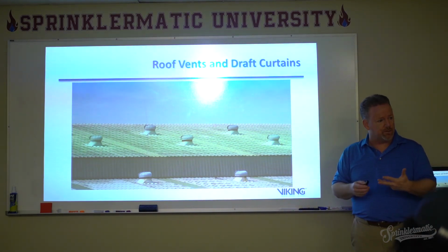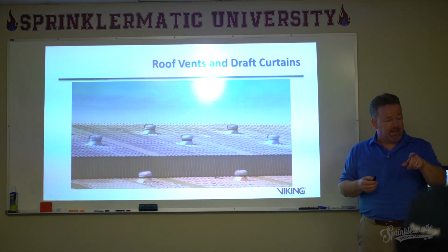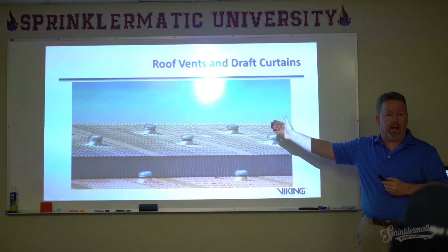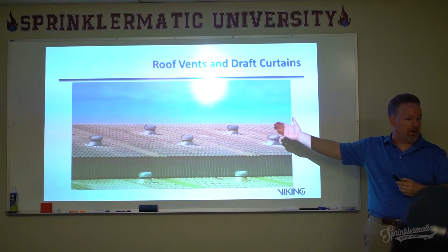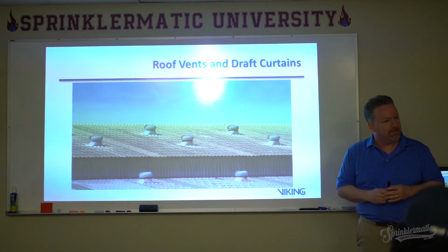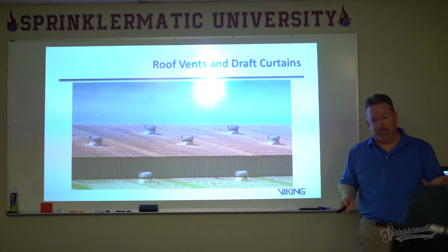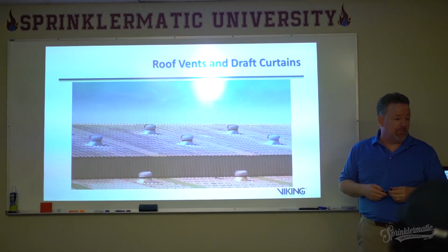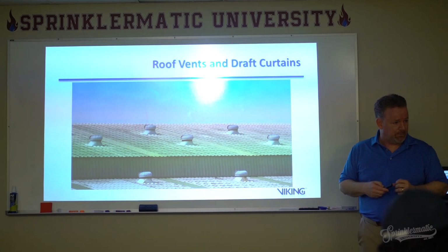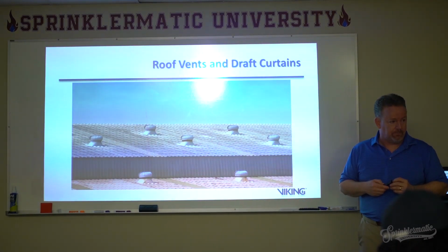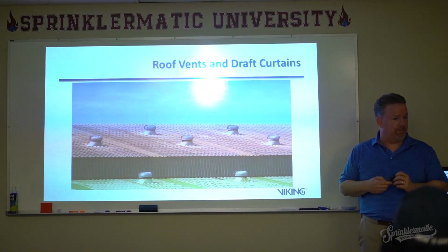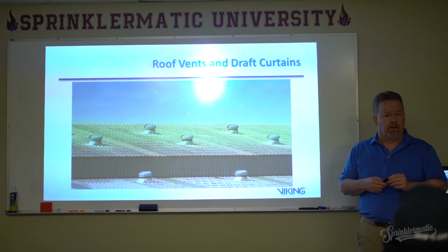It creates a situation called skipping. On the other hand, if we have vents that are rated to go off at temperatures greater than what our sprinkler system is going off at, that's fine. Hopefully they never work, but they may also be automatically turned on. If you've got a vent over here and the fire's here, it'd be like a fireman cutting a hole in the roof in the wrong place. It could be that you have sprinklers going off where there is no fire. Got it. All right?